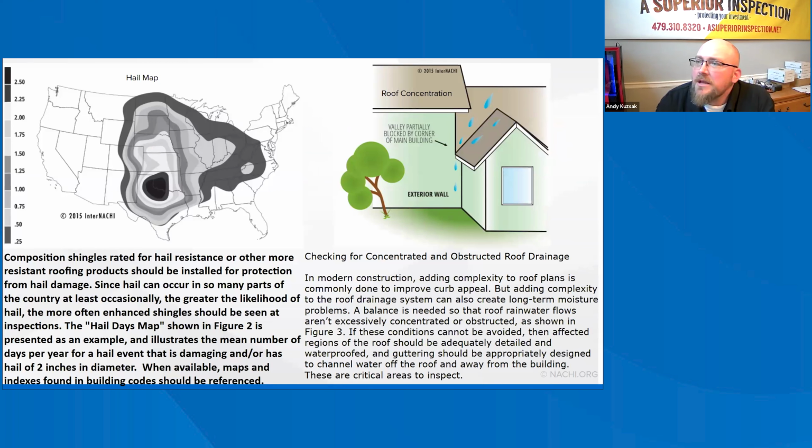Underlayment. So typically, 15-pound tarred felt underlayment provides backup protection against water intrusion only as long as the primary roofing materials remain intact. It is not intended for direct exposure, in the event of loss of the primary roofing system in a severe wind-driven rain event.